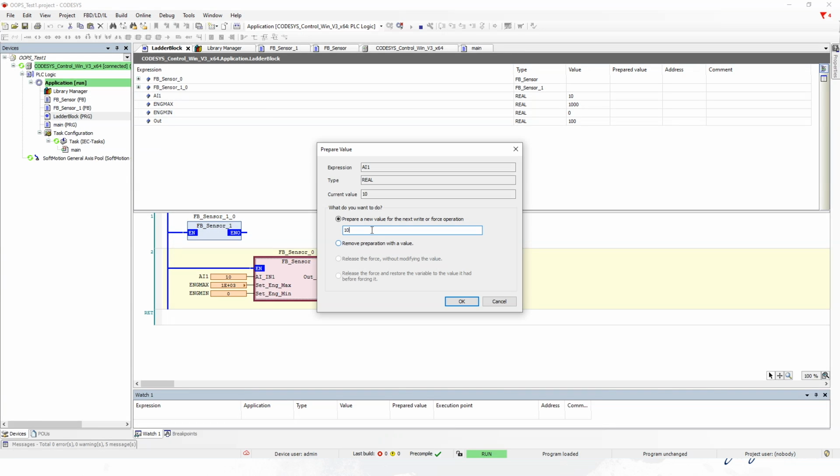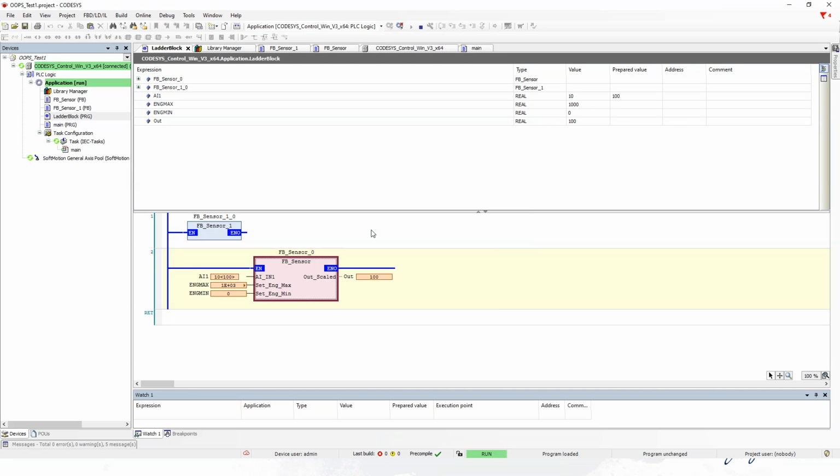So this is what exactly encapsulation is. We are using it in the PLC, but we call it only a function block. We treat it only as a function block, but it is defining one of the concepts of object oriented programming, which is encapsulation. This is how we utilize that concept in PLC code. So encapsulation is nothing but wrapping the whole code in one block and choosing what data we want to expose.